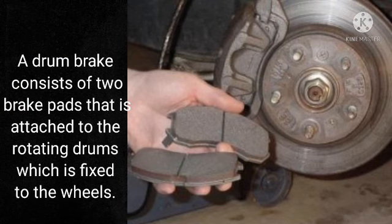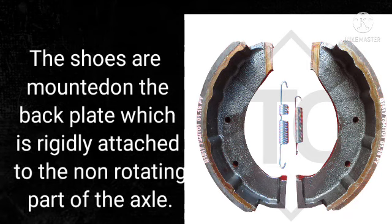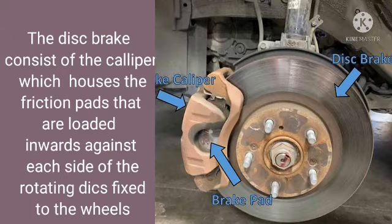The drum brake consists of two brake pads or linings which can be forced outwards against the inner surface of a rotating drum that is fixed to the wheel. The shoes are mounted on a back plate which is rigidly attached to a non-rotating part of the axle. The disc brake consists basically of a caliper that houses the friction pads which are loaded inwards against each side of a rotating disc fixed to the wheel.